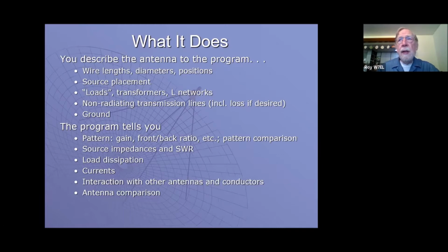And I defy you to find a professional engineer that does these measurements that will attempt to do a proof of performance without knowing in advance what the results should be. You won't find one, simply because the results can easily vary, again, several dB by simply standing a couple of feet in a different spot, or maybe putting the antenna between you and another tower, or many different variables.